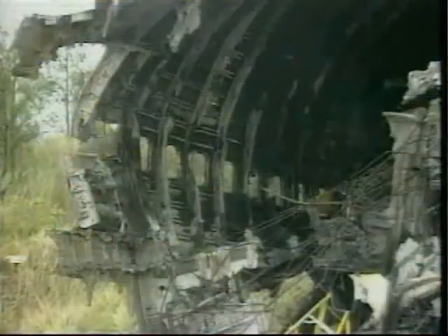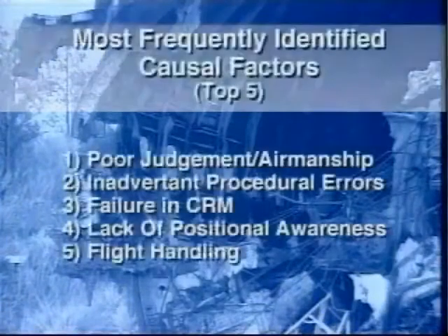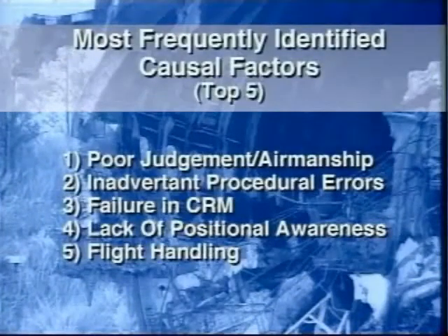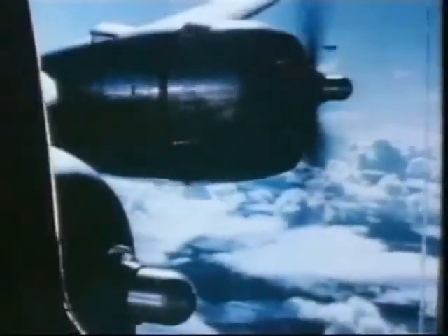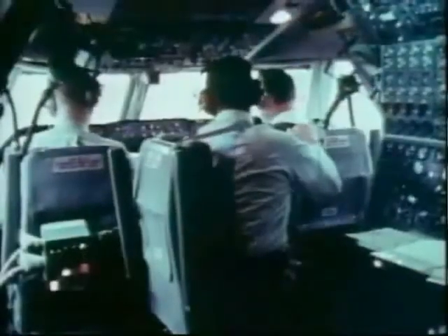In most approach and landing accidents, deviation from standard operating procedures was a leading causal factor. Your procedures have been developed and proven in order to assist and protect you, and you must use them. Decades of experience stand behind every standard operating procedure. Think of SOPs as a series of rules that, if followed, prevent incidents and accidents that have occurred in the past. A number of standard operating procedures deal specifically with approach and landing.